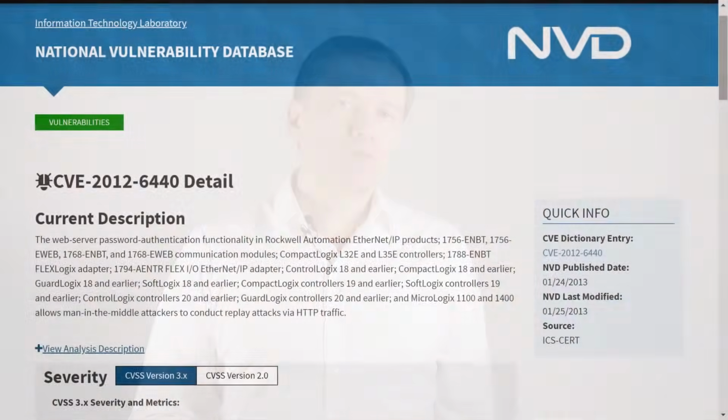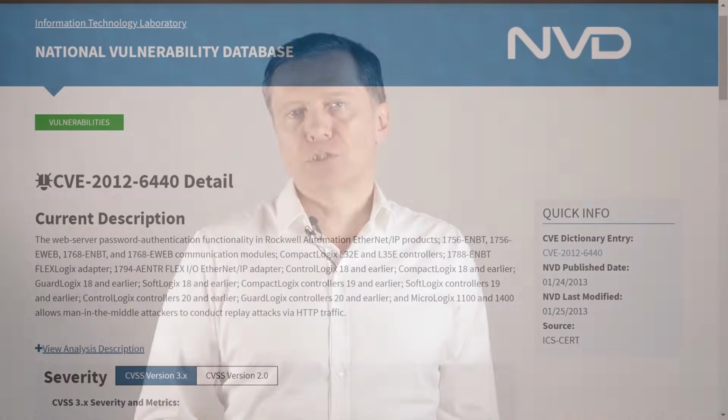This insight is of practical relevance. It means that it's often a waste of time to fix CVEs in the firmware or OS of automation devices. A good example is embedded web servers in automation products, of which there are plenty. These web servers are notorious for buffer overflows and related crap which can be used for infiltration. However, fixing those would be pretty much pointless. The bottom line is, before you devise your vulnerability management strategy, consider that the biggest vulnerabilities do not show up as CVEs. CVEs only cover bugs that can be patched or neutralized with a new firmware version.